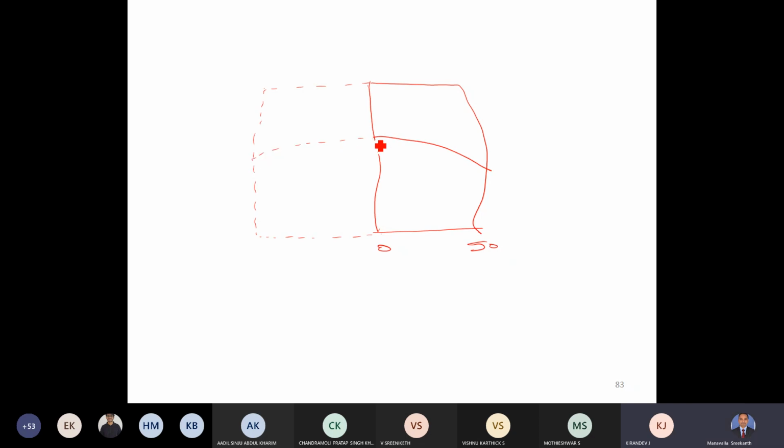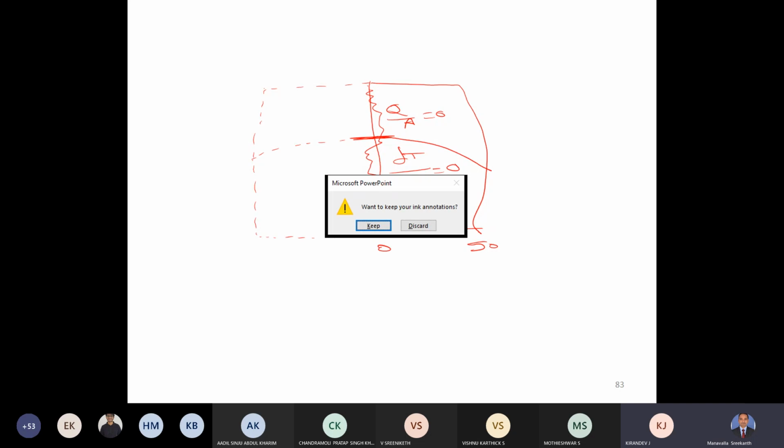That is because at this point there is no heat flux. That means this surface acts as an adiabatic surface, as if it is perfectly insulated. Therefore, there won't be any heat transfer on this surface. So here Q by A is equal to 0, which implies dT by dx is equal to 0. Okay, so this is how you can solve this problem.